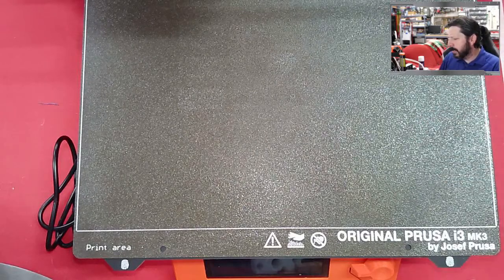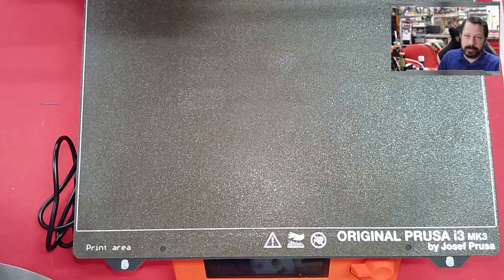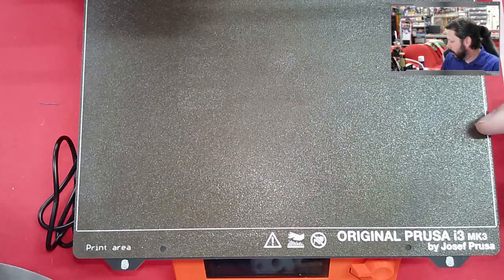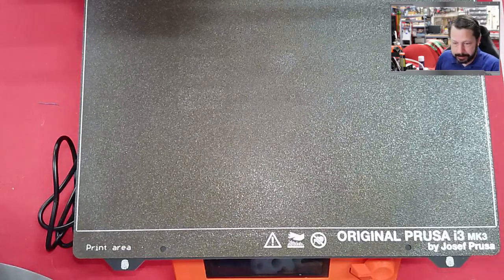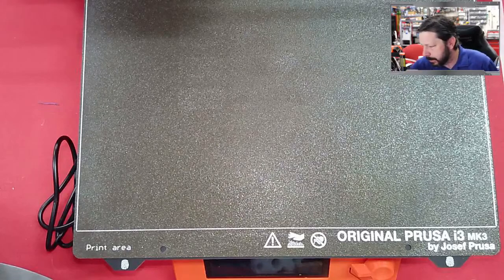I don't think I would use that steel wool on one of the flat PEI sheets. I've never done that. That PEI is very thin on most of the sheets I've ever used, and I'm afraid I would scuff through it. This one is actually kind of powder coated, so it's thicker on there. And so you can do that refreshing a couple of times. All right, many times so far. I've used that one many times.